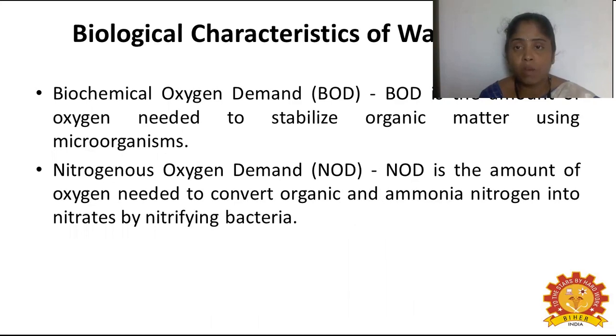When you talk about the biological characteristics of wastewater, what is BOD, the biological oxygen demand? It is the amount of oxygen needed to oxidize organic material with the help of microorganisms. COD is the amount of oxygen required to oxidize organic material without the help of microorganisms. The BOD measures how much oxygen is needed for organic material to be oxidized by the action of microorganisms.